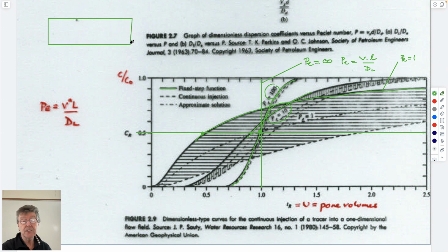If you imagine having a core with a whole bunch of layers in it, where these are high velocity layers, say sand in clay, then if you think about plug flow of a core going through this, you might think that they would preferentially give you these little advanced fingers of stuff, so that this is concentration equal to 1.